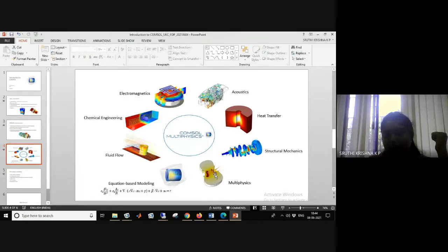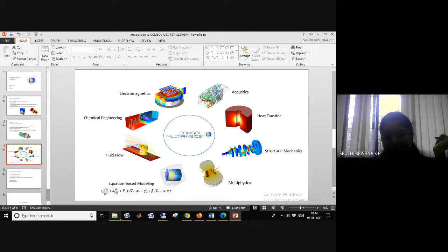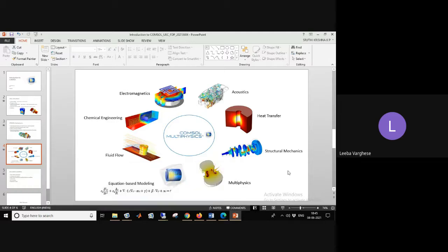Tell me, are there instances when this console doesn't support multiphysics? For example, suppose I'm working in a plasma module, and I try to add heat transfer to it. Sometimes it is transferred by radiation. Since the input values are not similar, multiphysics doesn't work.